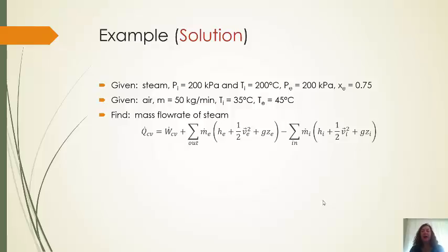Now, my first law. I have this expression here. So the heat transfer, when I consider both fluids at once, I assume that the exchanger is well insulated and all heat goes from one fluid into the other and nothing leaves the system. There are no moving parts, so work will be zero. I also am, because of the wording of the problem, plus this is very standard, I will assume that kinetic and potential energy are negligible or zero.